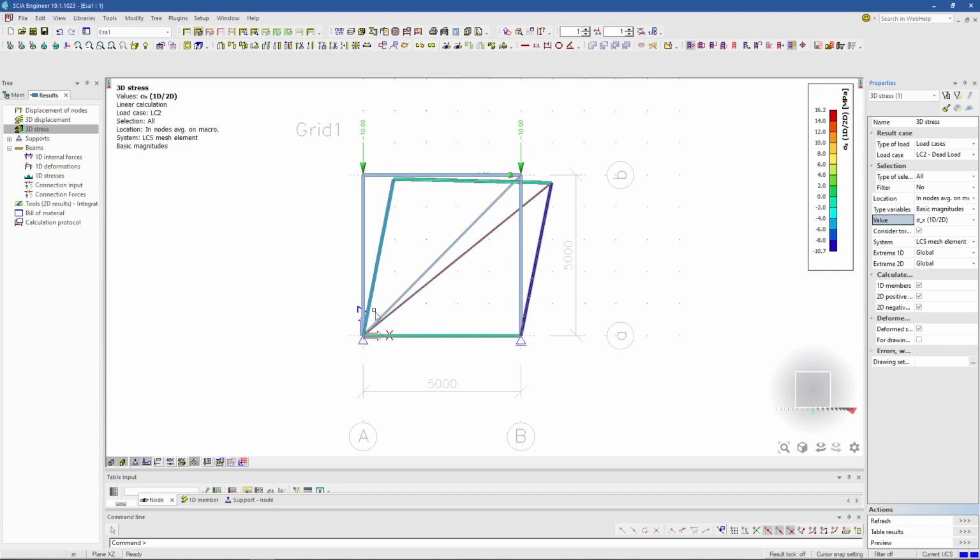So you can see from observation, this is in tension, this is in compression, this has been increased. Looking at this, since it's been decreased, then looking at this, not much has changed. So these members are in compression, where this is in tension.